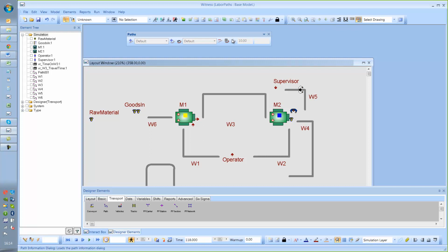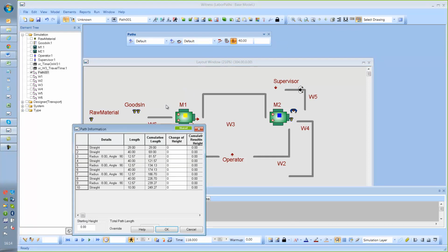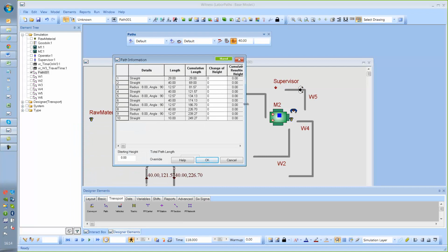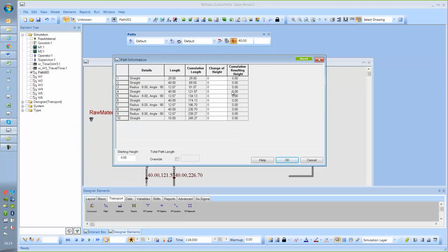And we also have some information specific to our path, which tells us what we've added in here and allows us, if we're working in a 3D world, to change it so that at some stage here we actually have a height gain of 2 units, so we keep going up in the air along the top and then back down the other side by putting a -2 in.